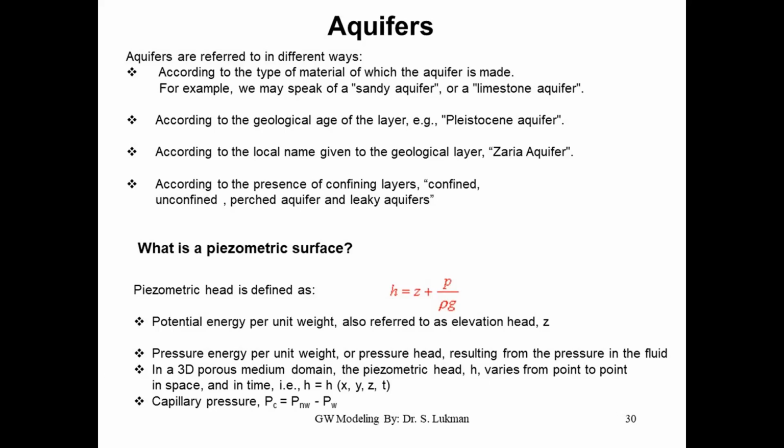By modeling here, if you have a contaminant here, let's say this is the direction of groundwater, how much time will it take for it to move from here to here? Because groundwater moves very slowly. Usually, you can find it at 0.2 meter per day. So you can imagine, 0.2 meter, that's like 20 centimeter per day. 20 centimeter, that's like this, per day. So it moves at a very, very low velocity.